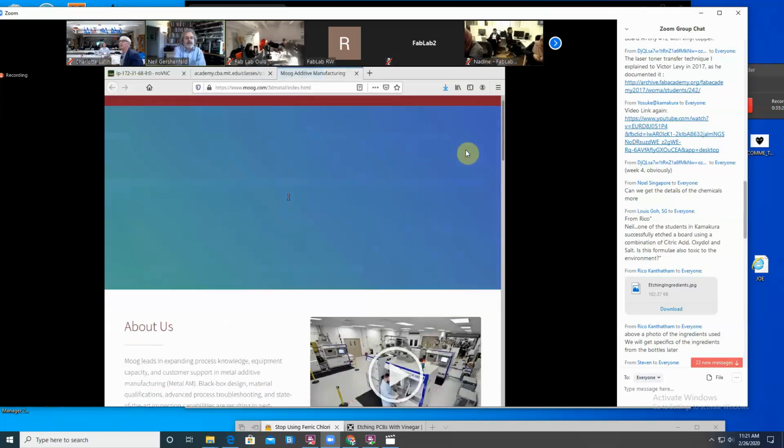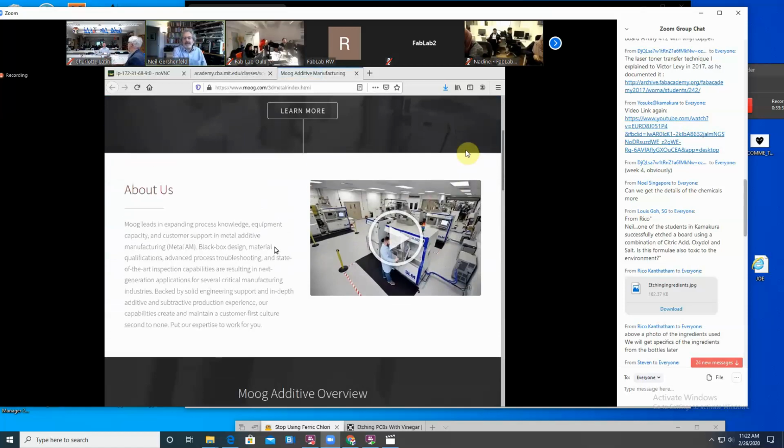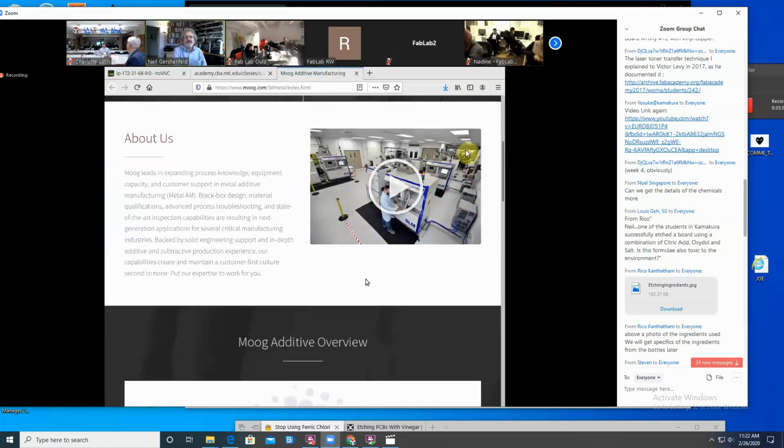This is a company I work with that does aerospace, and metal 3D printing is so important to them. They ended up buying out their vendors, and they manage this farm of laser metal sintering printers. Each of these is a $1 million class machine, you need to carefully control the environment, and each machine needs a support person. One thing that is emerging is a couple of startups working on extruding metal filament and melting it while you extrude it to do FDM metal, and those are coming.